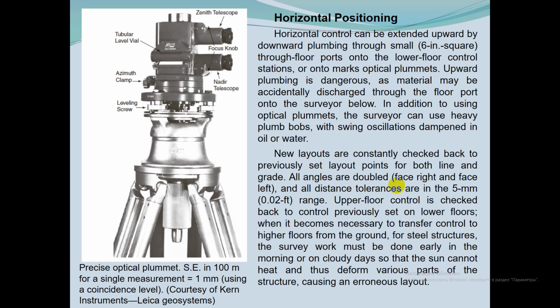structures. The survey work must be done early in the morning or on cloudy days, so that the sun cannot hit and thus deform various parts of the structure, causing an erroneous layout.